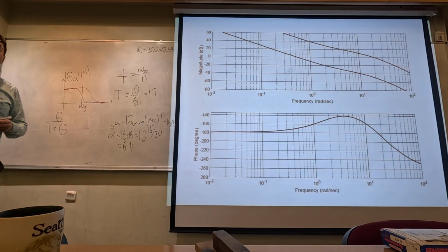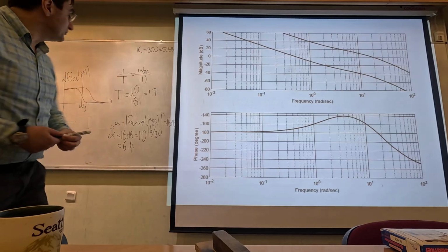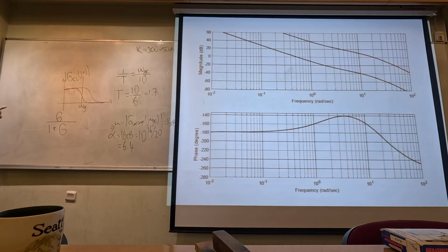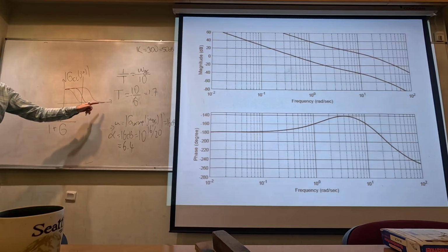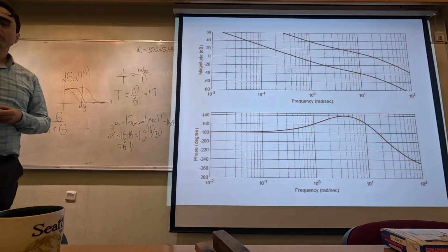Okay? And when we look at the lag compensator, in that case, we decrease the gain crossover frequency of the system. Okay? So a lag compensator would give us a low pass filter with lower cutoff frequency. Okay?